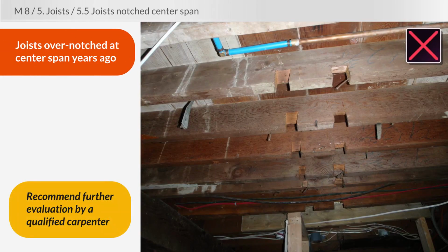Now this is a very old home. These joists were overnotched and at the center of the span, so you have two things going. The notches are too big and they did it in the center of the span. But that was done many, many, many years ago. And obviously, nothing has gone wrong for probably 50 or 60 years. Yes, you should probably still report this. Again, we don't know how your client plans to use the home. Maybe they do something differently that no one else has ever done and they cause the joist to crack.